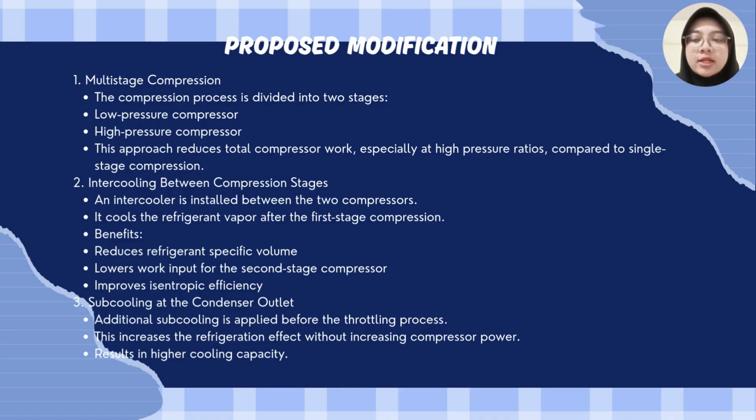Proposed modification. First, multi-stage compression. The compression process is divided into two stages. Low pressure compressor, high pressure compressor. This approach reduces total compressor work, especially at high pressure ratio compared to single stage compression.